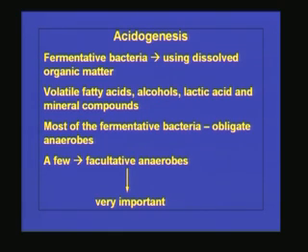So who will be able to take care of this oxygen? Because this oxygen is toxic to the obligate anaerobic bacteria. They will not be able to perform in the presence of oxygen. So who will be taking care of the dissolved oxygen present in the wastewater? The bacteria responsible for that are the facultative bacteria.